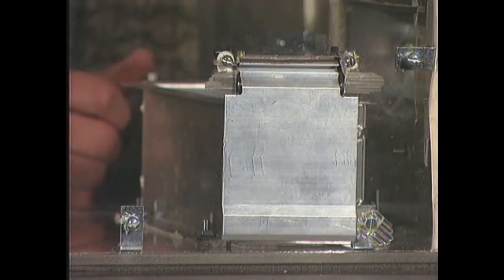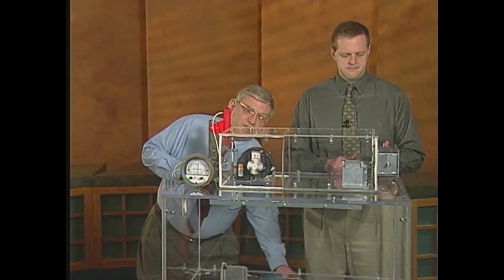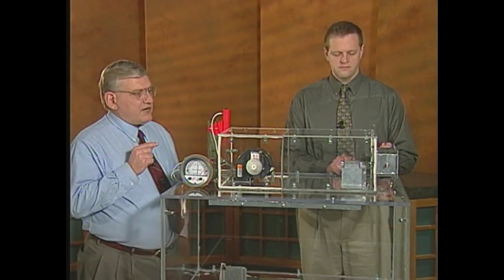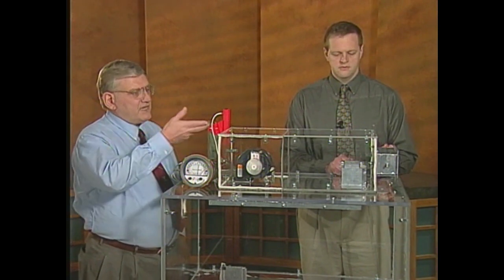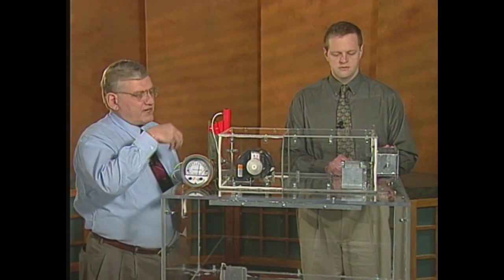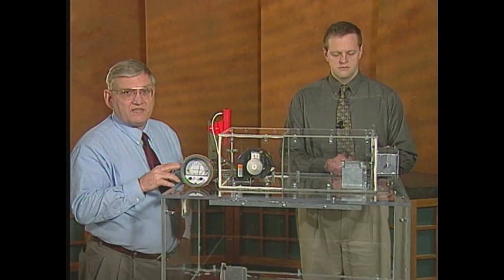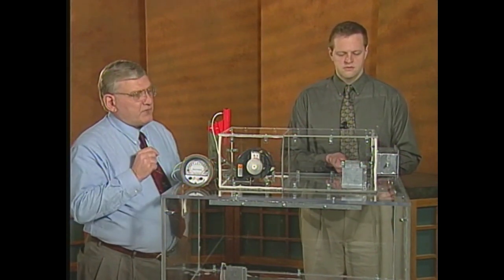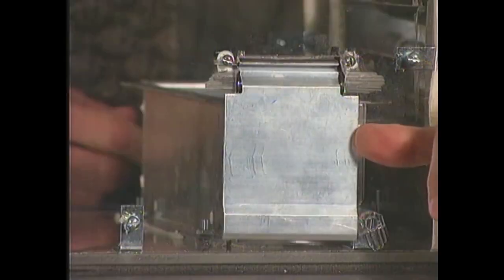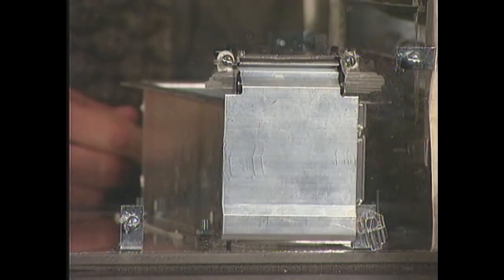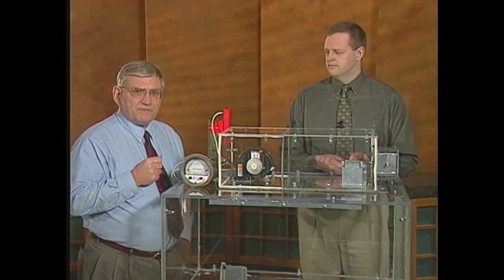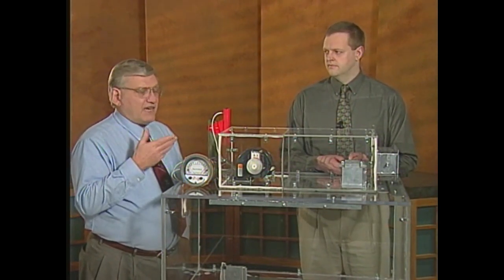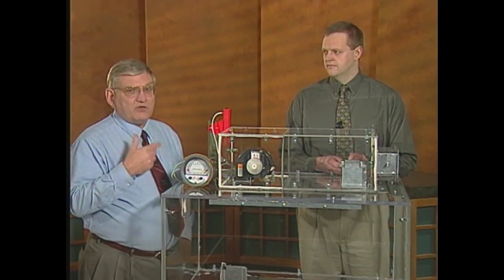Okay, then we're going to turn on the supply fan to full air. And John's going to increase the outside air to the space. Now, as he does, the supply fan will take the outside air and put it into the space. We're noticing the building static pressure start to go up. But yet our barometric damper simply does not open. Why? Because it's located after the return air damper. It's in a suction side of the air handler. In fact, that damper will never open up. You don't need to bother with it.